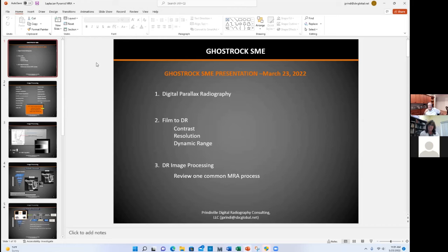And the more you do that, the more you take out the random distribution that is the noise on an image, that's the random flux coming from your source. So you can basically average that out and do much better than you can with CR. CR also has the disadvantage that it has grains in its imaging plates, and those grains also add noise to your image. But in essence, they're considered to be better than film. But DR is, again, a step above that.